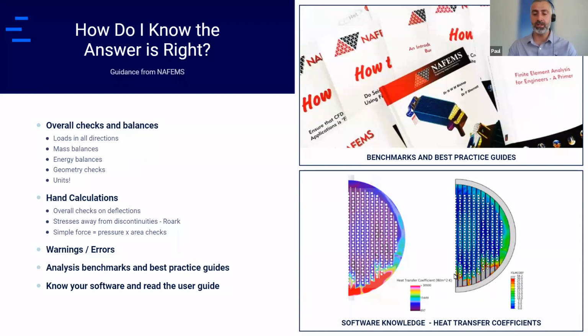So you can see that in order to have a valid set of boundary conditions in my FEA software, I had to know two things. I had to know that I couldn't just export the default heat transfer coefficient. I had to use the local heat transfer coefficient with a reference temperature. And the second thing I had to know was I had to modify the units so that they were consistent across both packages. Otherwise, ultimately, you would have got a result that was effectively meaningless.